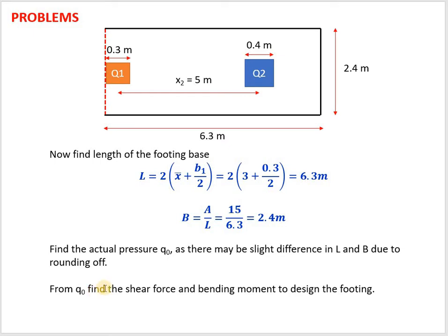So you have the loads, you have the pressure, and based on that you find the shear force and bending moment, and design means you have to design the depth of the footing as well as the reinforcements and all. So for that you need to find the shear force and bending moment. But as far as exam point of view and your syllabus, you need to find only the dimensions of the footing. So your job is finished here. Once you find the L and B, your job is over.